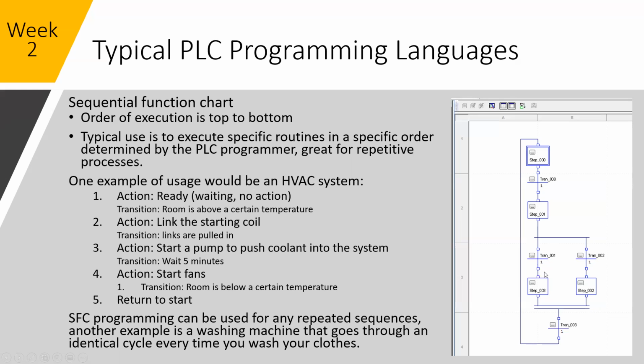So if your coil is pulled in down here, we'd be waiting for the temperature of the room to come back down. This could be something else. So if this is coolant pressure and the coolant pressure is low, and this just starts the coolant pump, then it'll run. And as soon as the temperature gets low, all of your coils are going to drop. So once this transition's done, we're going to stop even looking in this code. So this is kind of the be all and end all.